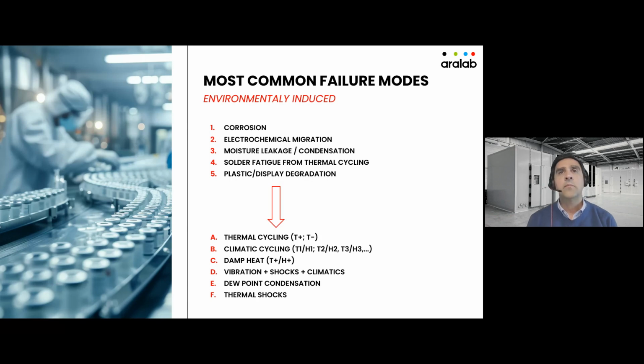Okay, so I'm thinking of some examples from the past that we have been dealing with include, for example, the antenna from cars or trucks. It's a very small component. Unless we are in the automotive industry, we hardly think about the antenna, but it's actually a very delicate and complex component of the car or truck. Okay, so there's a very systematic set of tests that we have to conduct on that particular component. Of course, dew point condensation, I've already addressed this, and thermal shocks.